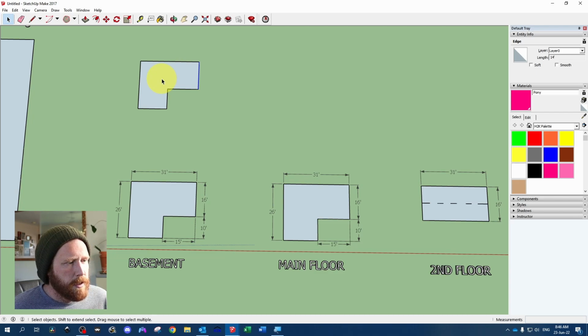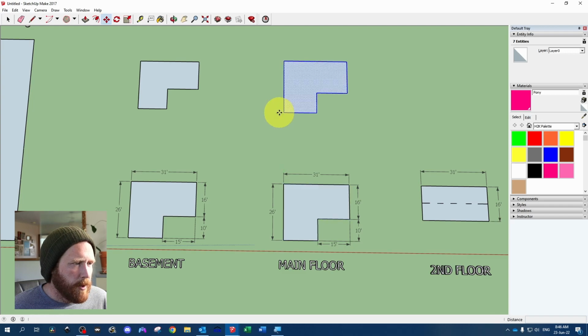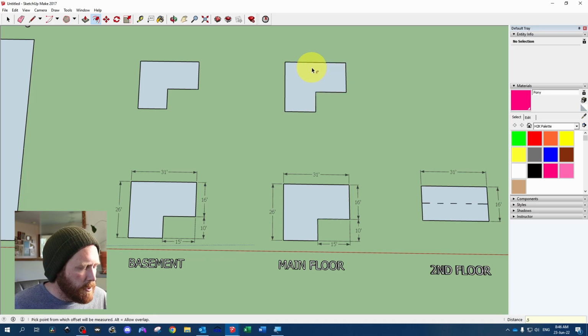So that's good. And then this is also going to be considered exterior. And rather than redraw it, I'm just going to double click it, copy, paste, and then we'll just offset this. So if you have exterior measurements for your main floor, you want to pull in, offset by 1/2 foot. So you can type 6 inches or 0.5, enter, delete our exterior.